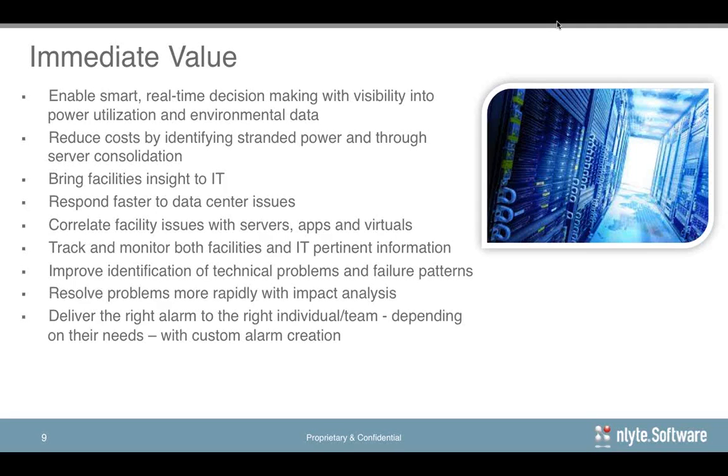Resolving problems impacting, again, showing power distribution. This is a nice feature in the application because within FieldView, you can look and see what devices are powered from what facility power outputs. So by hovering over a cabinet, you can see up the power chain and see what PDU it's coming from, what panel it's coming from, and vice versa. I can hover over a panel and then see what racks it's supplying power to. And that really is important for maintenance, for troubleshooting, and making those things available so that you can do some impact analysis on if I'm taking down a PDU, what impact does that have on the downstream users.